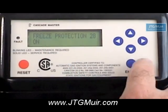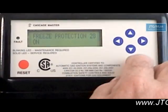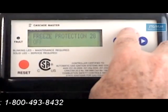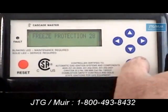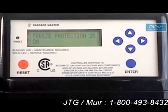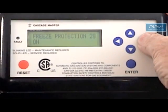You may choose to turn that off. You can do that by hitting the enter button and then going the up or down button. In most applications you would leave that on. The only reason I can think of not doing that would be if this was a snowmelt application and we had cold water constantly going through the boiler and we did not want it to run when we weren't giving it a command to operate.